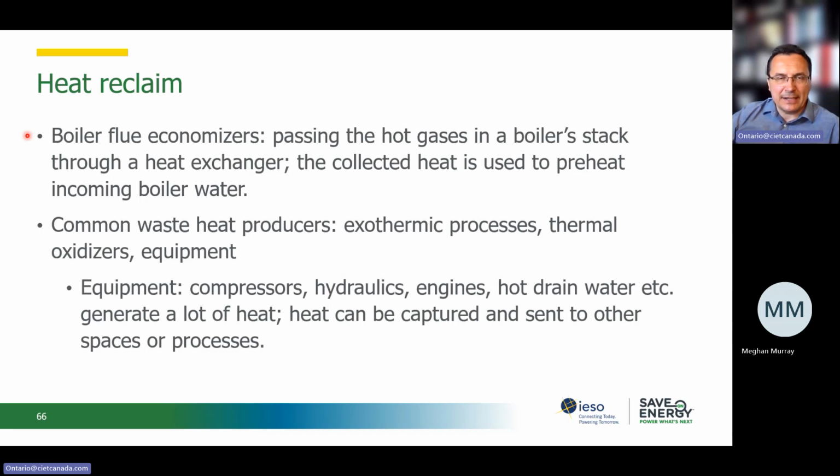Boilers emit combustion flue gases, and these flue gases passing through the boiler stack are exhausted in the atmosphere, in the outdoor air space, with a significant amount of heat, especially for those that have vapors from the combustion reaction present in the flue gas, without condensing that.